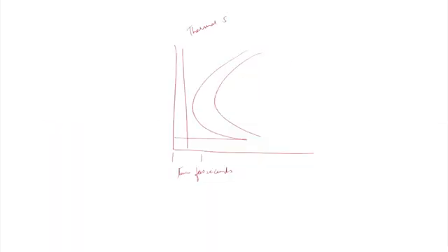Suppose this is, let us say we are discussing the TTT curve here, and this is my martensite start temperature. Usually for plain carbon steel, the time required to miss the nose is in a few seconds basically. So, I have to have a very high cooling rate so that I miss this nose. Now, when you have a very high cooling rate, you are bound to introduce a lot of thermal stresses.